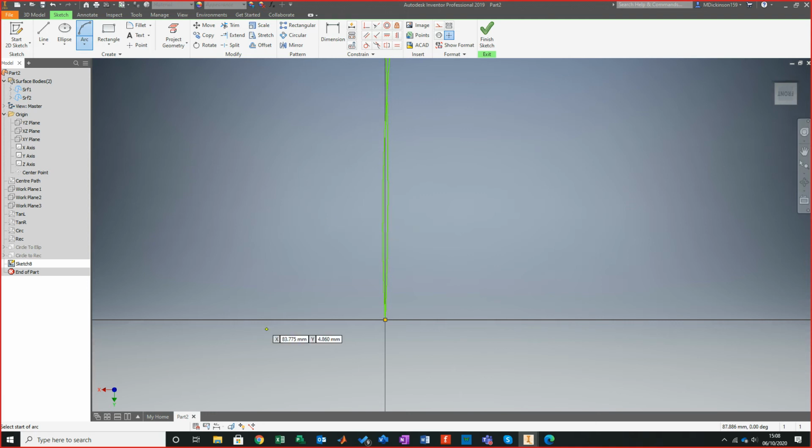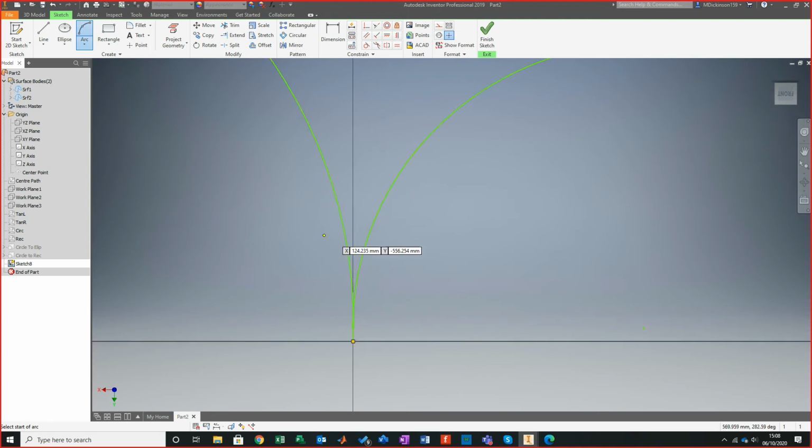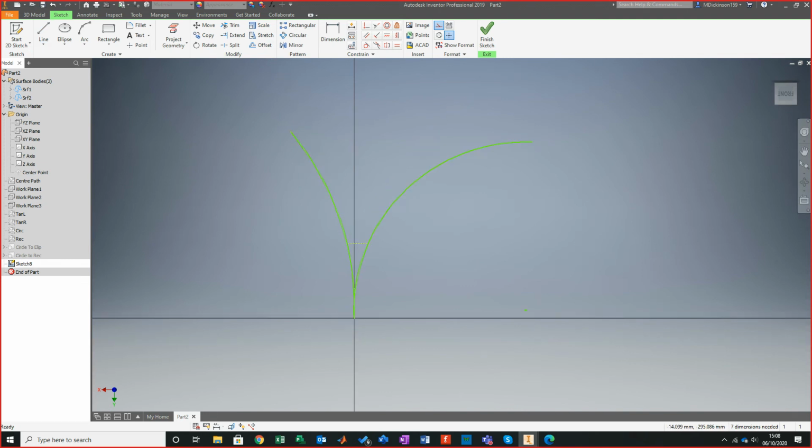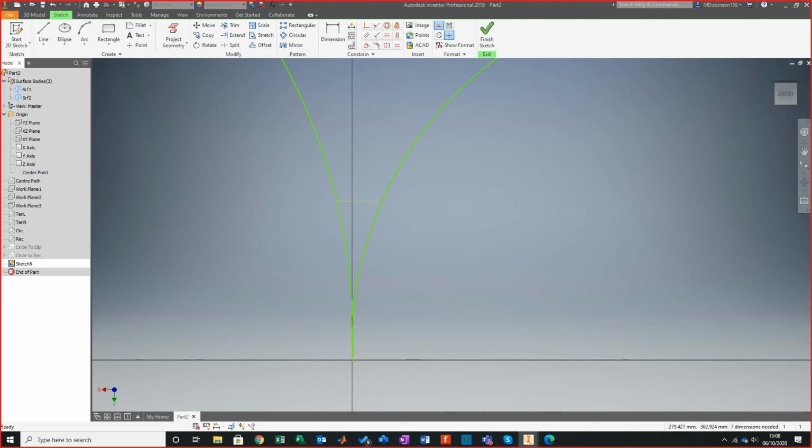What it's actually referring to is that, let's say this line that I'm about to put on here is the obvious reference to our geometric database. What it's saying is anything beneath here doesn't count. So the system tries to say, oh, that looks like a big bit, I'll get rid of that. That looks like a little bit, I'll get rid of that. And it keeps trimming it down until it gets something. Now, what this can end up being is little tiny surfaces floating in space. These little tiny surfaces are needle surfaces, and they're an error in the subtraction between two component sets.